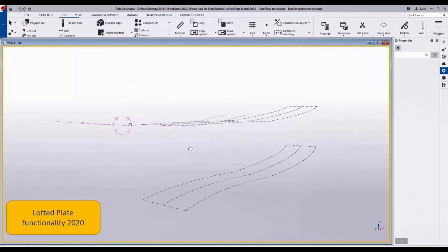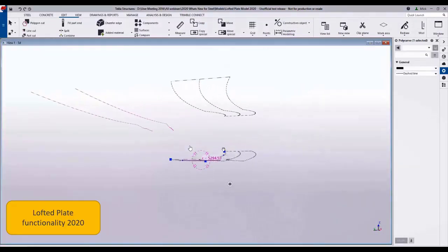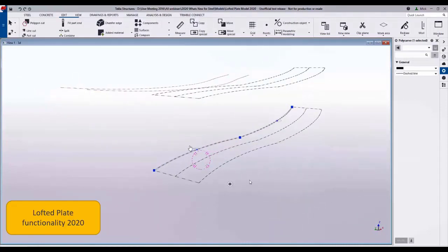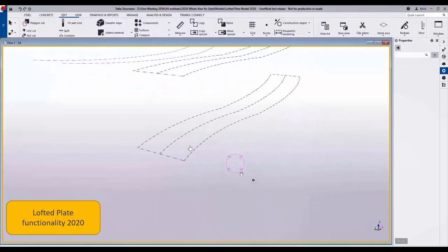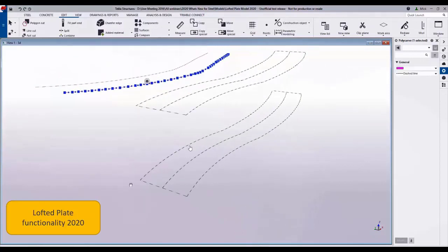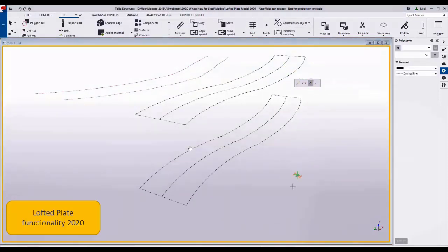So smooth flowing drawing objects, polycurved objects, quite simply by drawing the polycurve using either a tangential arc or simply from point to point. So here I've created tangential arc objects to define the top and bottom flanges, and here I've used a from point to point option. To use the polycurve option, quite simply select it.